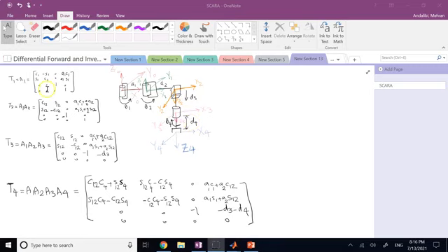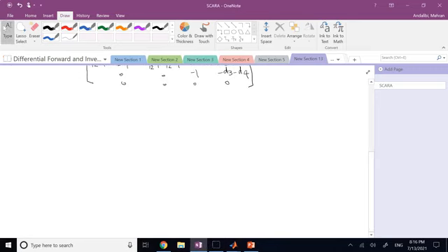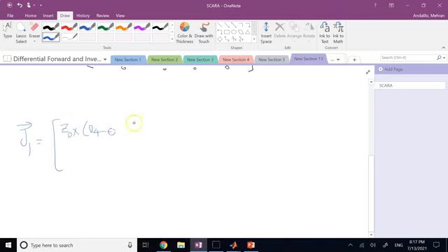These are the T matrices from T1 to T4, and now I can use the third and fourth column of these matrices to calculate J1 to J4, the 4 columns of the Jacobian matrix. So if I want J1, well, the first joint is rotary, so it is going to be Z0 cross O4 minus O0, and then Z0.